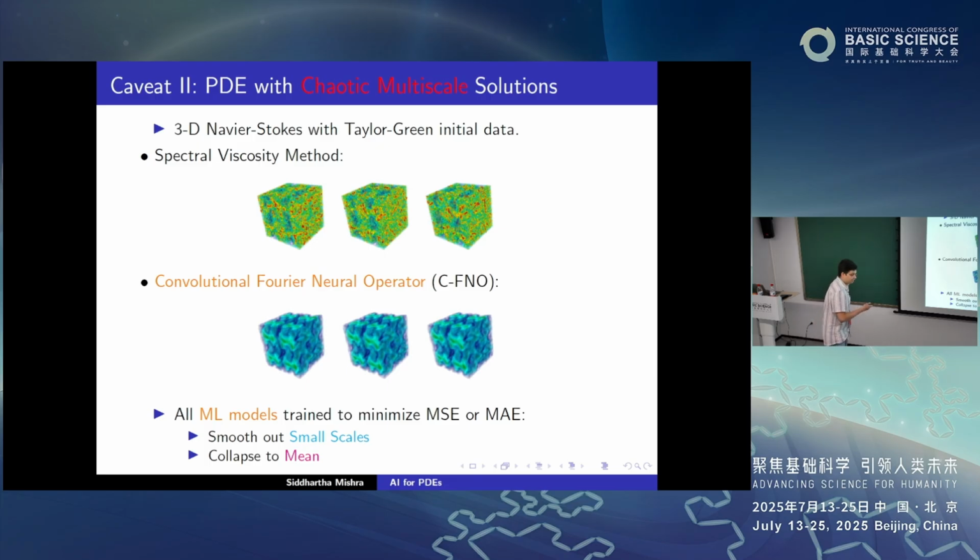is a standard fluid dynamics problem, Taylor-Green vortex, 3D, solved with the spectral method, direct numerical simulation. So what you see here are three plots, right? You take the initial condition for the Taylor-Green vortex, you make tiny little changes, and then you get these three tiny changes, and you get these things, right? So first of all, you see that there is a lot of small scale information. There's a lot of small scales that are happening.